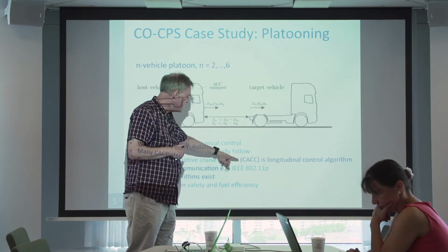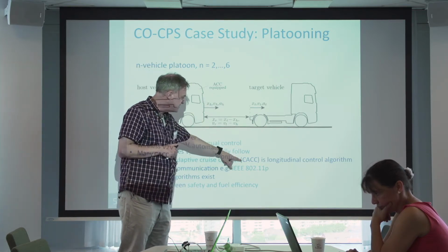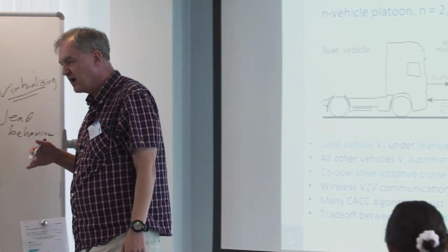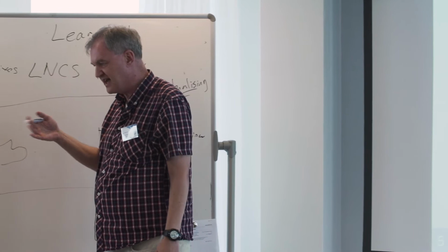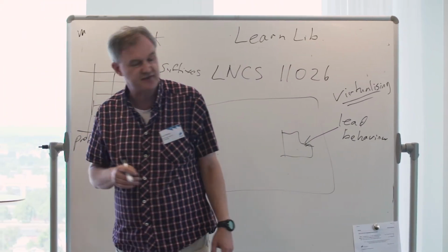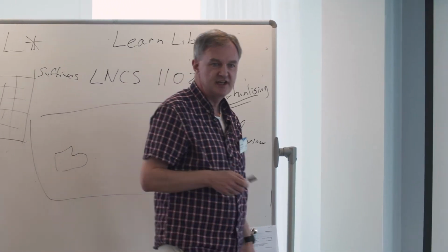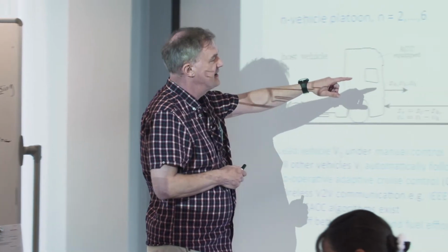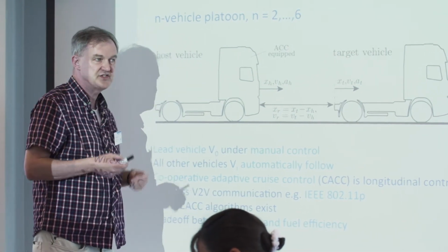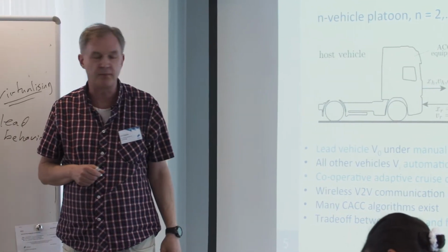They're refinements of ACC. Here, in this particular simulator, we're going to use CACC, cooperative ACC, which is a wireless approach. So either you could use the radar to detect the distance, with the noise issues that involves, or you could use the wireless with a GPS sensor. So each vehicle can just relay its distance or its position to the follower vehicle. Of course, that's also subject to noise, but it's a different kind of noise problem, okay?